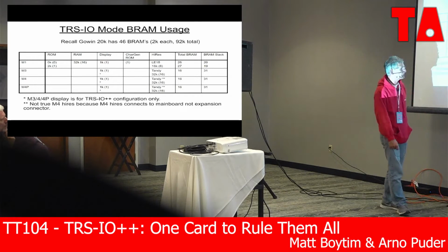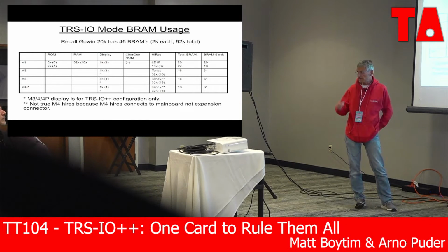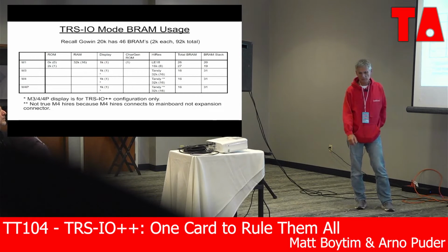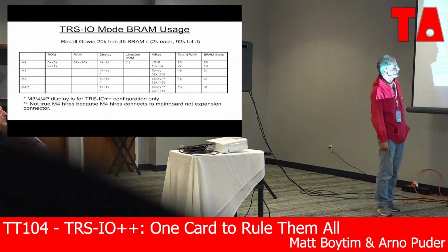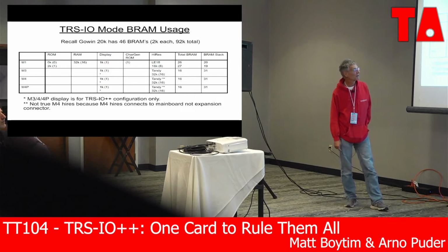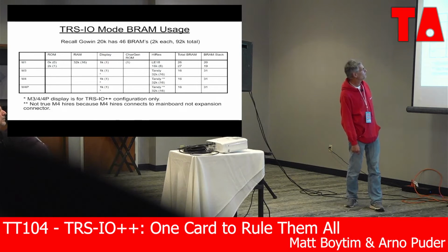We have the high resolution graphics. For the LE18 graphics, it's only 16K. For the other graphics, we have enough memory that we can implement the full Tandy, which is 32K. So the total BRAM, you can see the column 26, 27, 16. So we have plenty of BRAM, right? There's 42 total, so we're plenty. And so the slack is the extra. So a positive slack means you have enough, a negative slack means you don't.